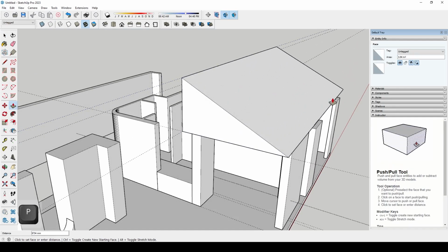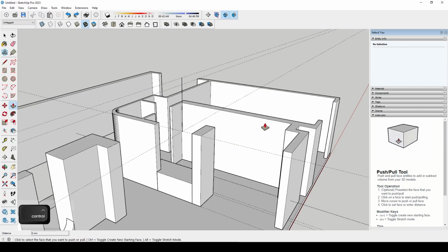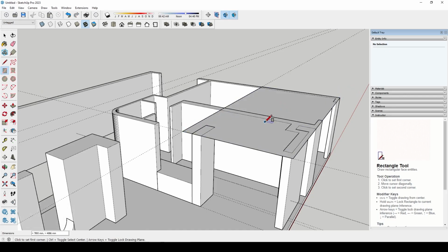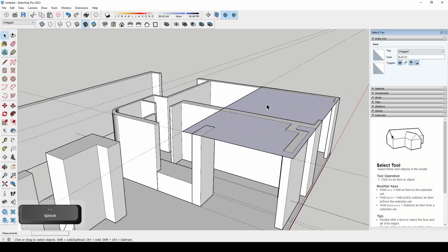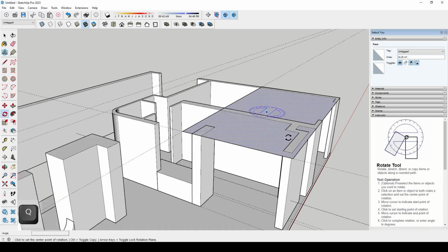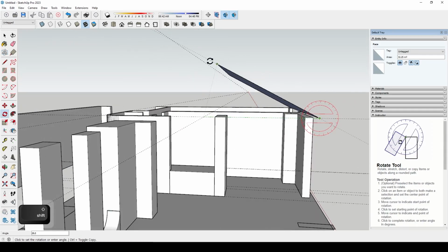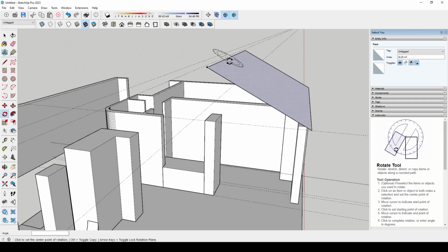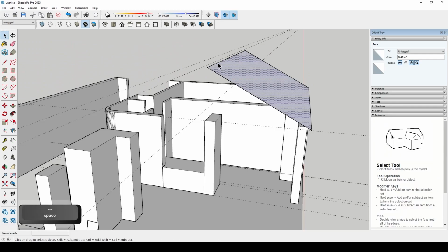We could, and I'm going to give you multiple options just in case you guys have got different houses and need to do different techniques. We could go across from here, Q as our rotate, hold down shift to lock it to that angle, go up and then get it until it's going to snap onto that axis. And then once we've got our line selected, M for move, we could move that up to this point here.